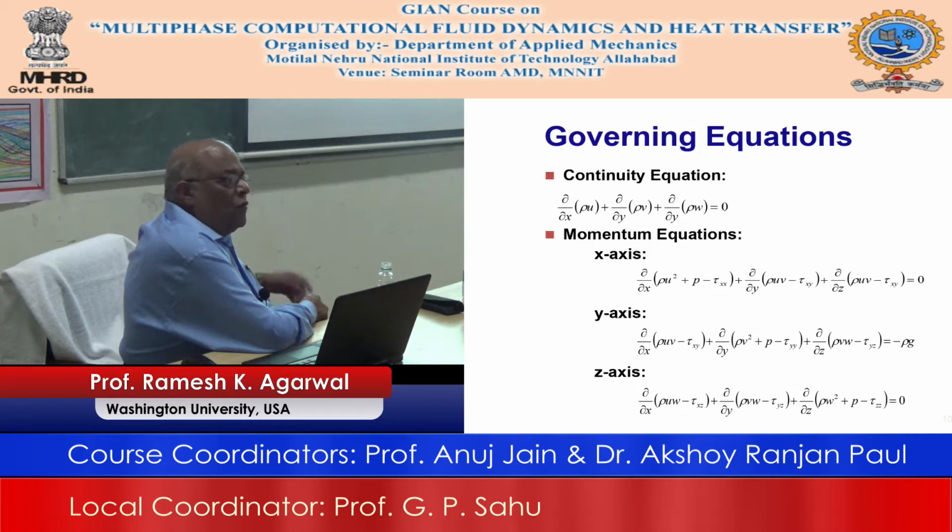So you have to know before you use Fluent why you are using it, to get the right answer in the shortest possible time. But don't forget about the mesh independence. And then, as I said, you have a Boussinesq approximation, rho is constant, use the SIMPLE algorithm, and then there are variations of SIMPLE: SIMPLEC, PISO, and this and that. But to keep life simple, just use SIMPLE, and that is good enough. And you can use a pressure-based solver because it is incompressible flow.